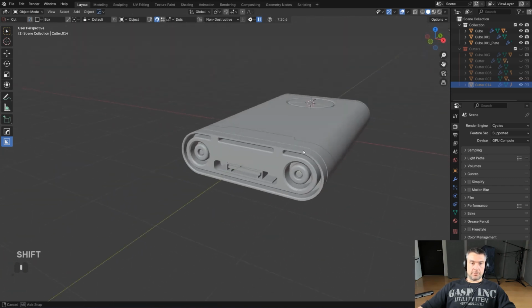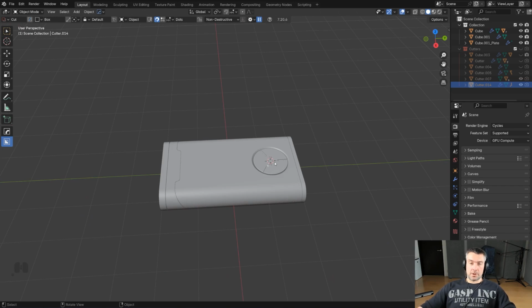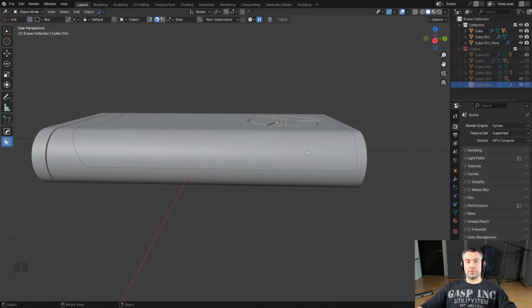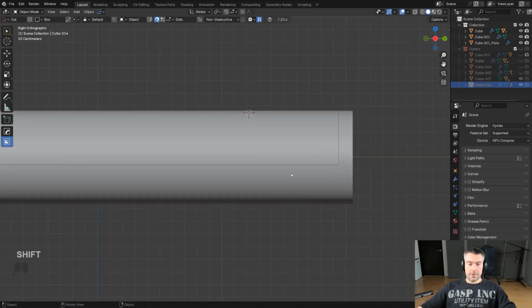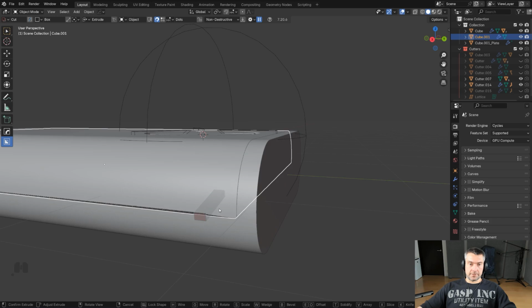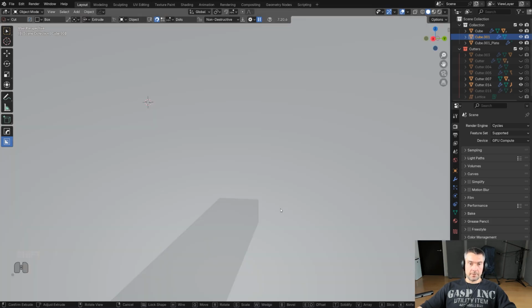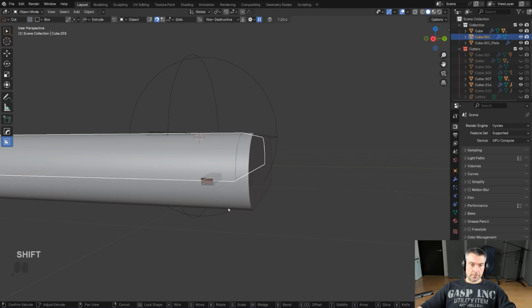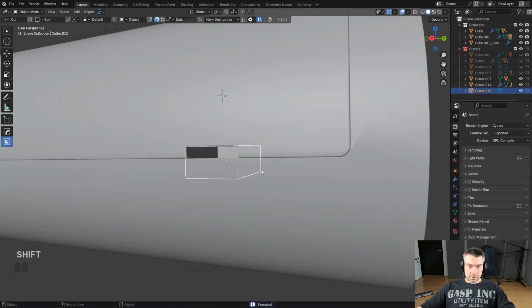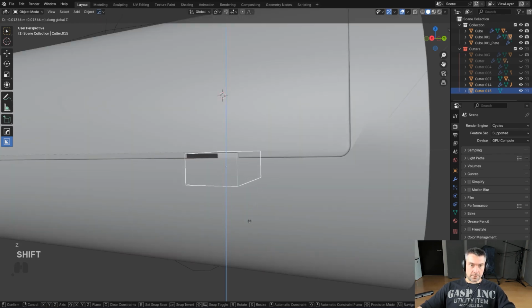And this kind of brings us to the tertiary detail stage, more or less, because these are still secondary details, but we're slowly starting to encroach on the tertiary detail stage. So for example, if I went here and started to create some small cuts like this, not too deep, something like that. Let me just cut it in here, hold Shift, and drop this one down a little bit to some kind of reasonable height and move it outside, to create this kind of a nudge.